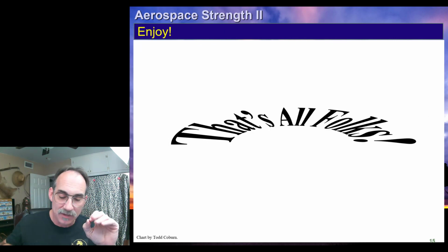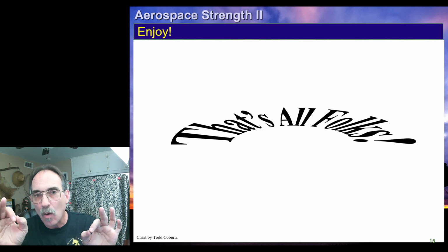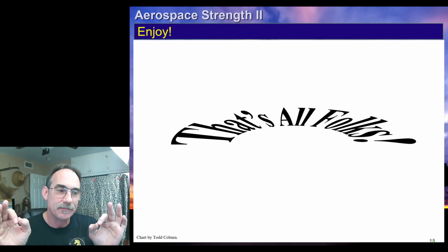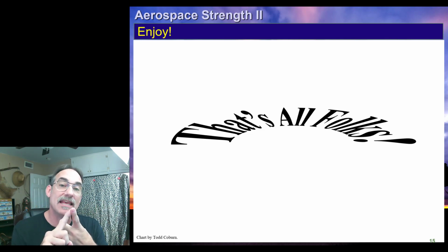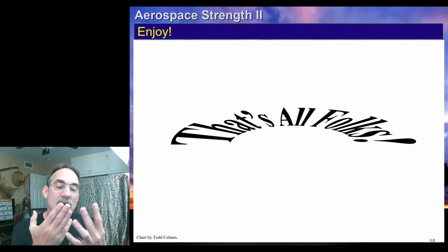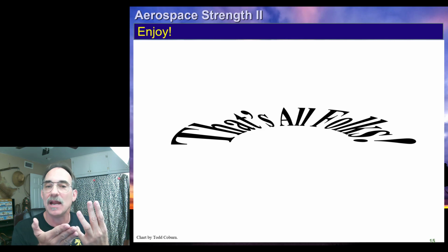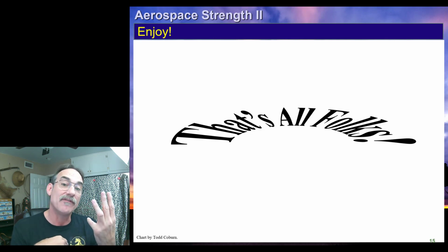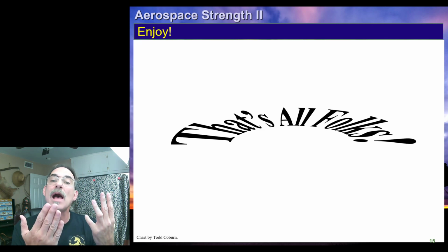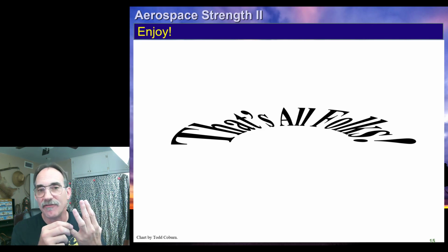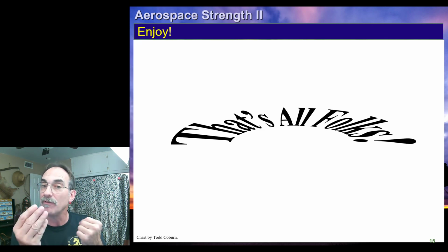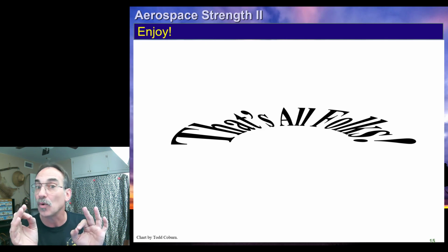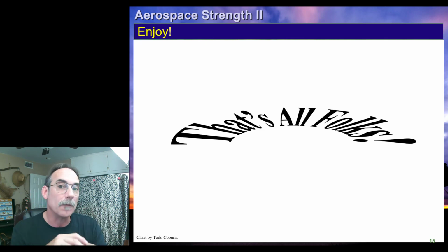Okay, so you now are armed and dangerous. You know how to calculate the effective width of skin using three methods, one for preliminary design, one for early design, and one for mature design. You know how to calculate the inter-rivet buckling allowable, and you know how to adjust the effective width of skin if the inter-rivet buckling allowable is less than your crippling allowable of the stringer.